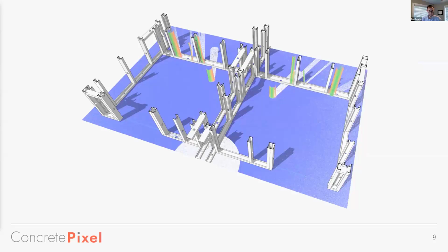So anyone who's been fortunate enough to work with a scan of a slab or a concrete pour knows there's a number of issues that come up and that can be addressed. Things like floor flatness, plumbing and electrical stub-up locations. This image shows the coordination between steel and plumbing. So you can see the plumbing stub-ups here. Most importantly, there's no conflicts with vertical studs. And like I mentioned earlier, studs are often aligned with trusses, so that can cause serious problems if they need to be modified or moved.